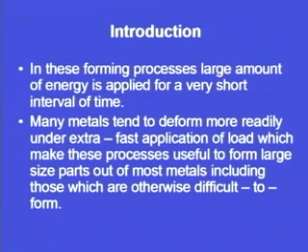Then many metals tend to deform more readily under extra fast application of load. Extra fast means that the time interval is very small, which makes these processes useful to form large size parts. So, another important aspect here is that we are going to make large size parts, or the versatility of these processes lies in making large parts out of most metals, including those which are otherwise difficult to form.